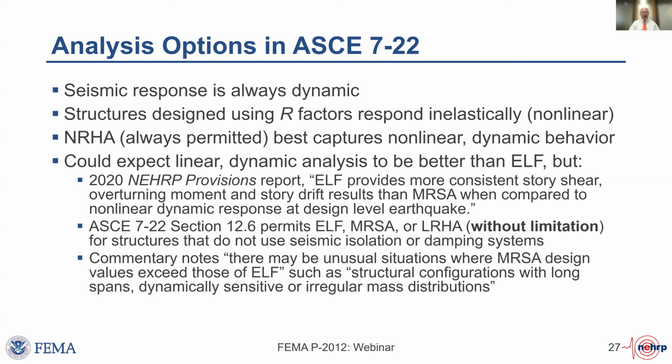Now, you could expect that linear dynamic methods are better than the equivalent lateral force procedure because they're more complex. They include an explicit characterization of the dynamic response of the building. But in fact, that proves not to be true. You may have noticed what the NEHRP Provisions 2020 report says, that the ELF provides more consistent story shear, overturning moment, and story drift results than modal response spectrum analysis.